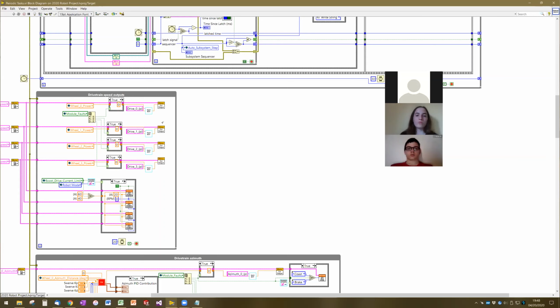It's giving a goal velocity. And when we're giving it a goal power, it is assuming that, you know, if you increase the power by 50%, you've also increased the wheel speed by 50%, and that's not actually true. The wheel speed and the power that's being applied to that wheel is not a linear relationship. So that would improve the wheel performance.